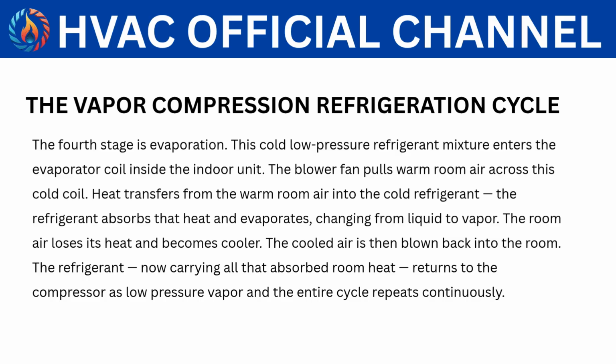The fourth stage is evaporation. This cold, low-pressure refrigerant mixture enters the evaporator coil inside the indoor unit. The blower fan pulls warm room air across this cold coil. Heat transfers from the warm room air into the cold refrigerant. The refrigerant absorbs that heat and evaporates, changing from liquid to vapor. The room air loses its heat and becomes cooler. The cooled air is then blown back into the room.